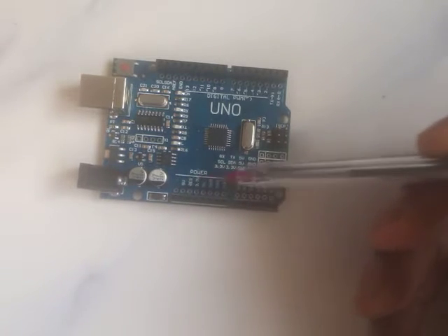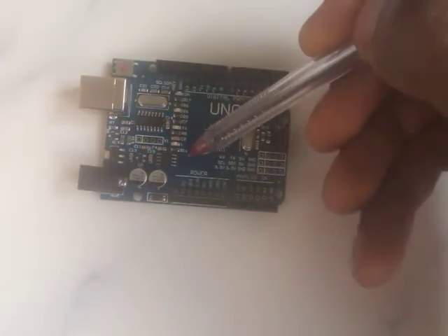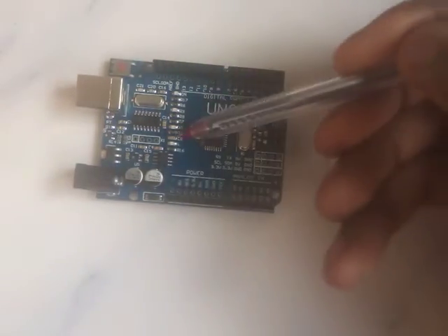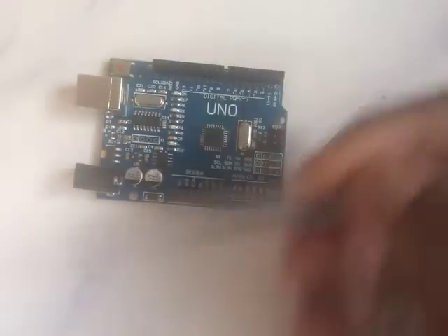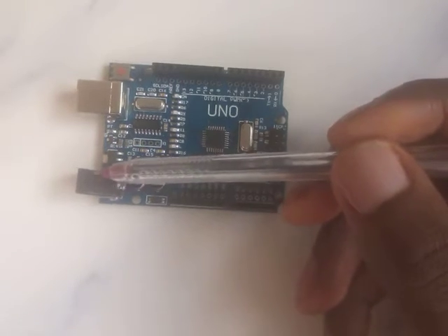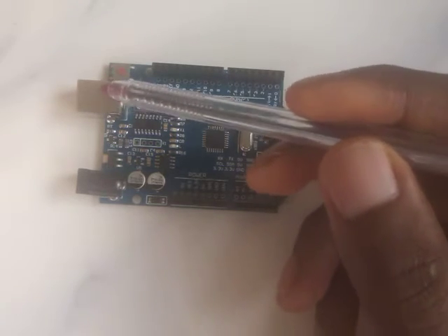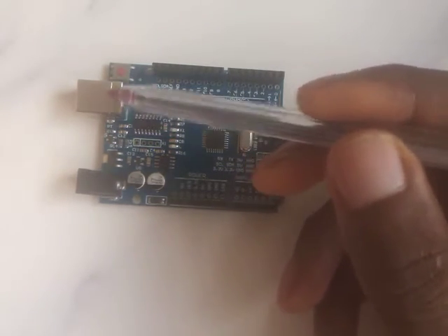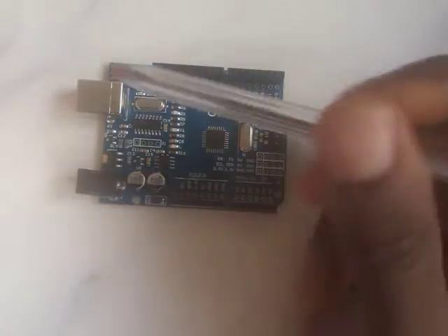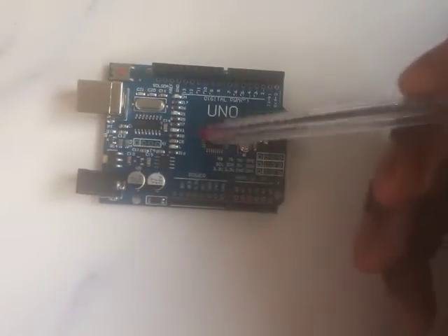The 5 volts and 3.3 are only used for powering devices with the board, whereby the board gives out power supply. But we want to power the board now using any of these three. So I'll be demonstrating using only this DC plug and V in. In later or subsequent videos, I'll be demonstrating powering the board through the USB, where we'll plug it to our laptop. This USB serves as both a power supply and for programming this board.